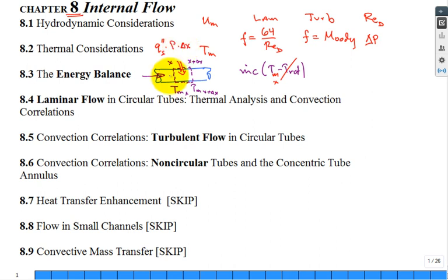And so you have the flows. Most students will trip on this. They won't, well, like, where did this, m dot C T, where did that come from, and why is that for flowing in? It's a rate at which it's coming in. And then m dot C T_m for the mean temperature going out. That's a loss or flow out. And then often you have a convection. This was an easy one for the convection from the wall.